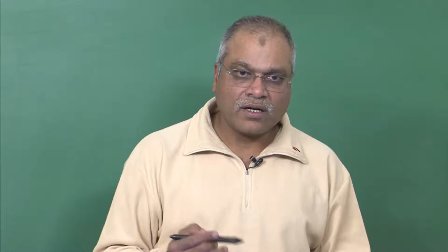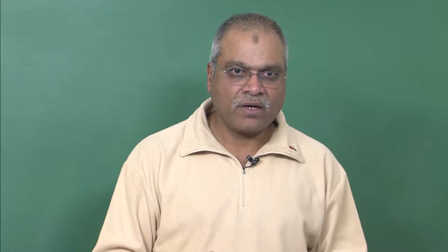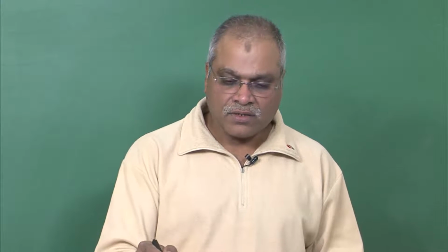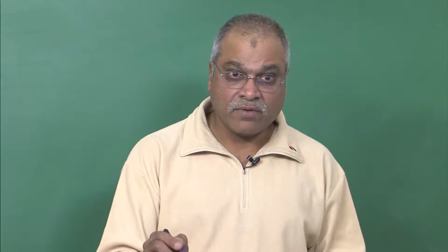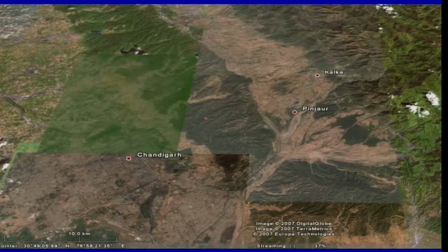So we need to know in which direction the faults are dipping and what will be the sense of movement on that. Just saying that my fault on the surface is not crossing the structure will not be enough. Where your structure is sitting with respect to the attitude of the faults is extremely important. Another one is here. In this case, this is absolutely not ideal.